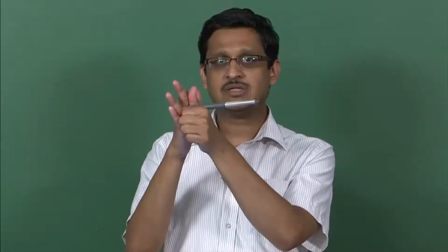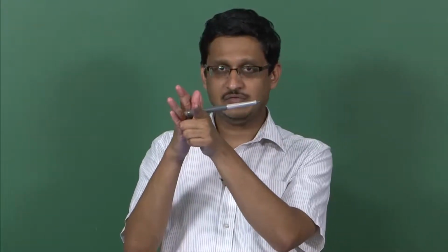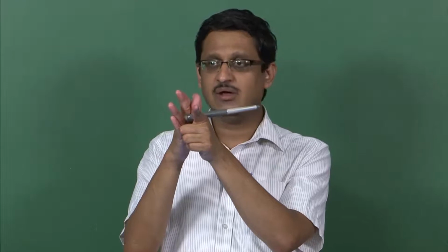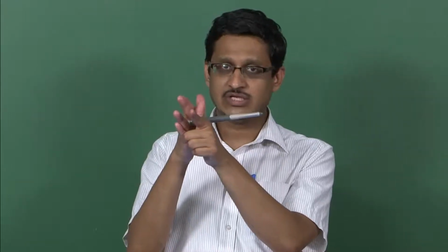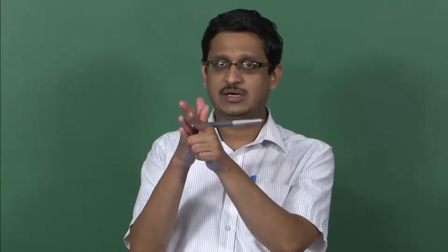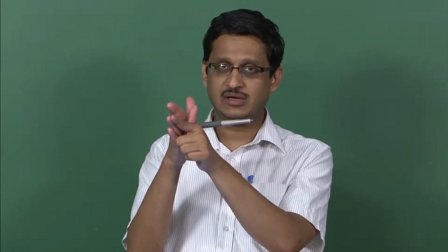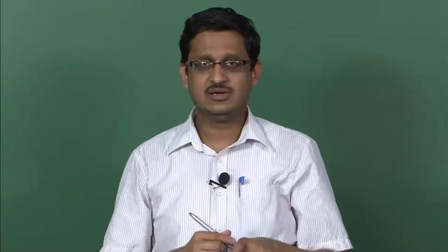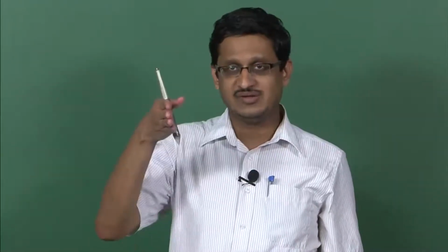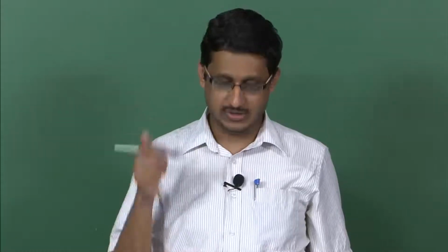For all times the tangential electric field must vanish, and the magnetic field, which is this finger, let us say, such that x cross y is along the z axis, the magnetic field H will have to generate a sheet current, a surface current, on this interface. To the left of this hand is the air, and to the right of this hand is the conducting material, and this separates the air and the conducting medium, and therefore forms the boundary.